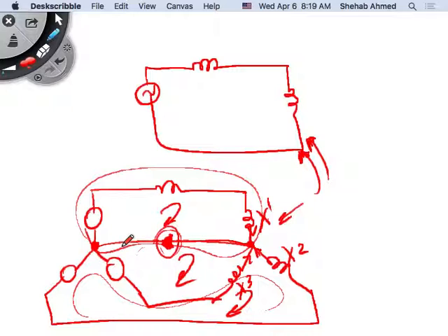But there's an additional benefit you get out of symmetrical components theory as well, is that you get some physical intuition about the system's performance. That is not possible when you merely look at a three-phase unbalanced system and just look at the numbers. So you may look at the numbers and see that the currents are unbalanced, okay? But you will not know if this unbalance is due to an increase on the load on one of the phases or two of the phases. You will not know that. You will not know if one of the phases is connected to ground or not through an impedance.